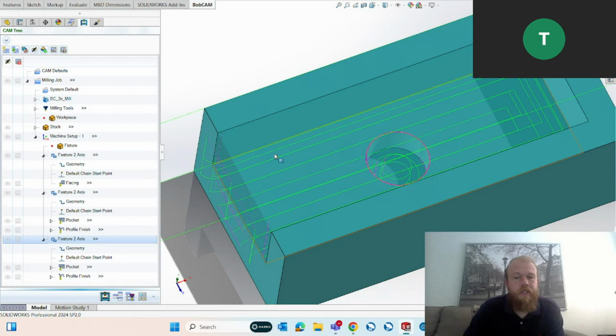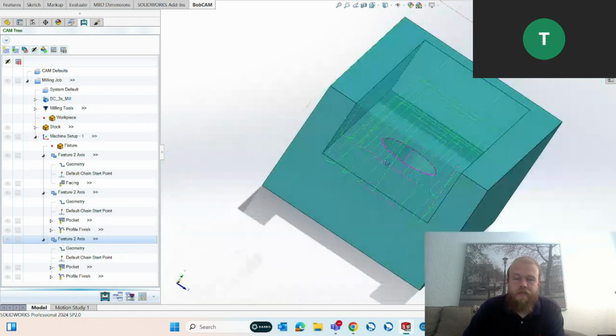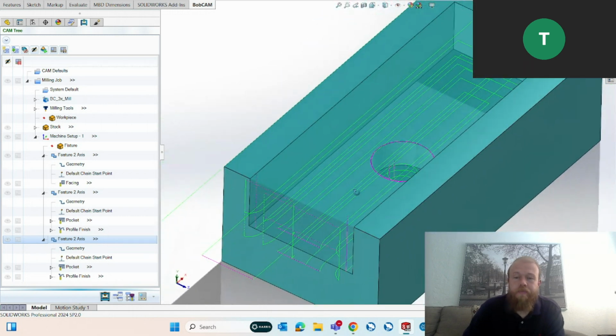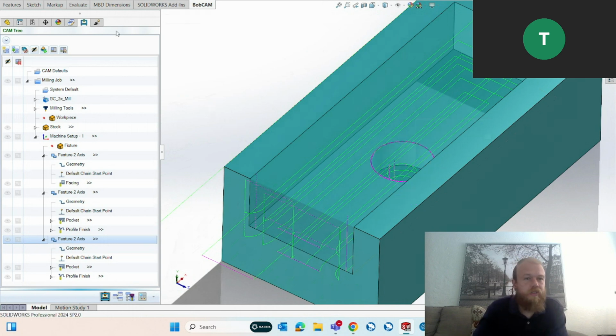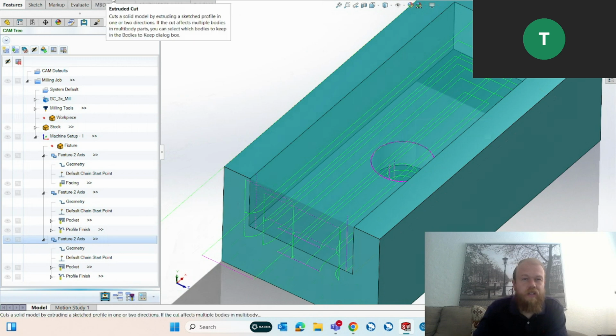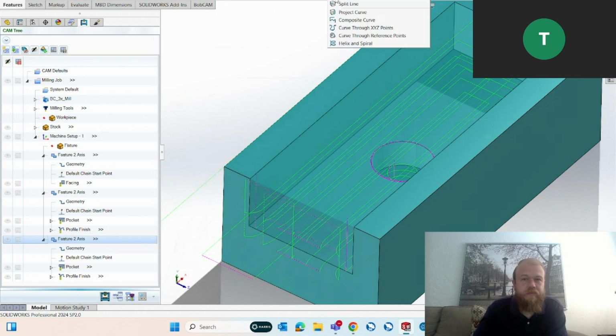Cool. And then we can go in. What do we have next? We have the design for a hole. So if I wanted to set this up as if I wanted to drill it and do a threading operation and things like that, I can go into my, I believe it's under the sketch function here, under the features, I can select it as a hole, and that is under that's a good one there. Oh, hole wizard. There it is.